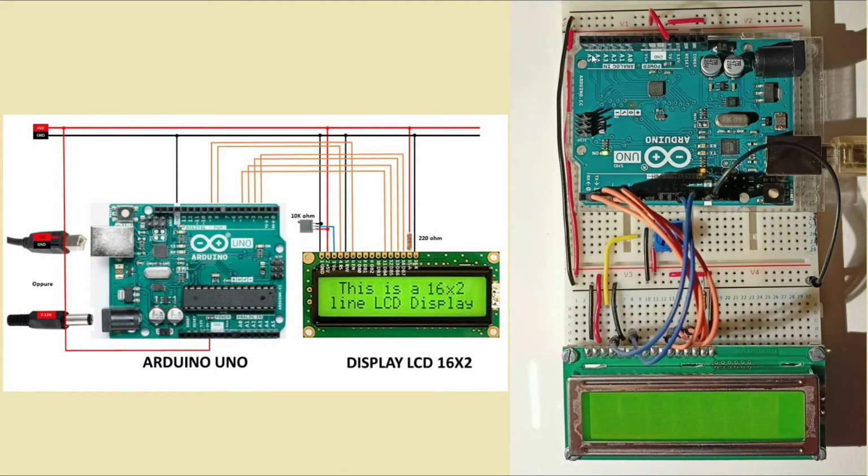So, let's see the connections on the breadboard right away. First I brought both black, which is ground, and red, which is 5V, to both sides. Then I connected them to the ground line, which is an uninterrupted line of pins connected to each other, both on one side and on the other, which has the V3 line, which is then jumpered on the V4, and I did the same thing on the V1 and V2. So these 2 red lines both correspond to 5V for me.